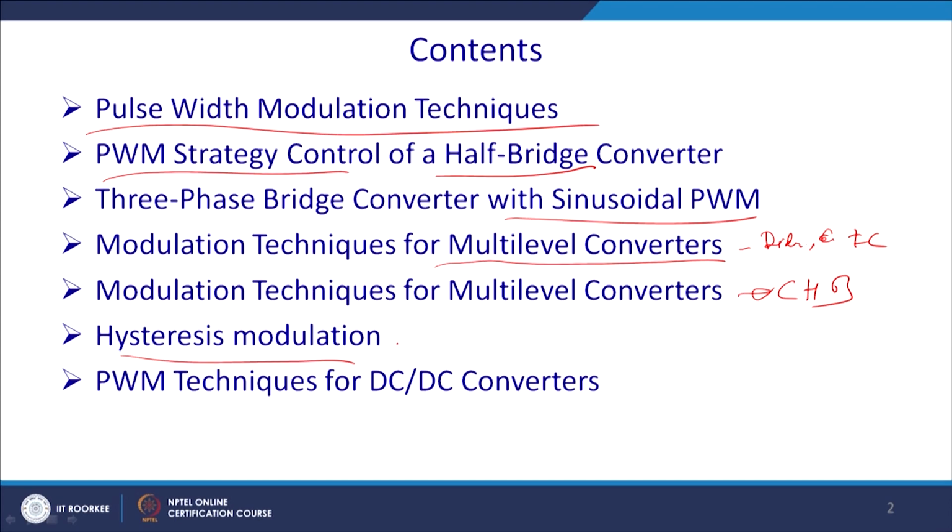Thereafter, we shall see the hysteresis modulation and PWM technique, not only for the AC to DC converter and DC to AC converter, or rectifier and inverter operation, but also for DC to DC operation.